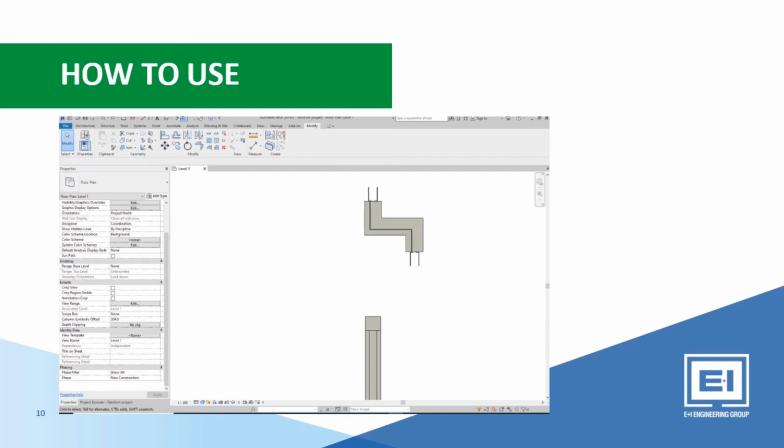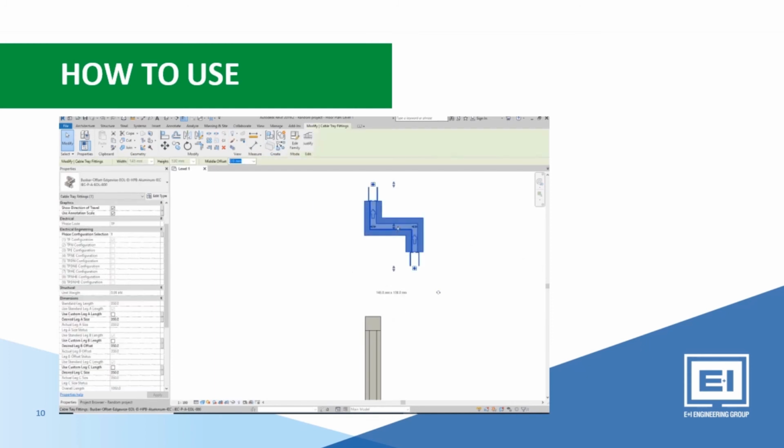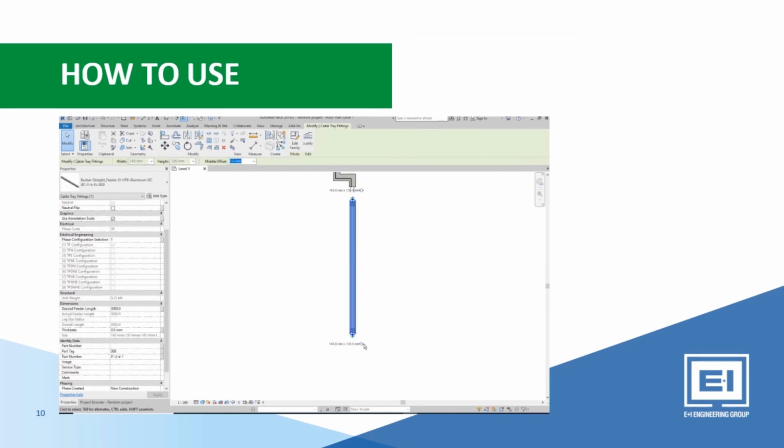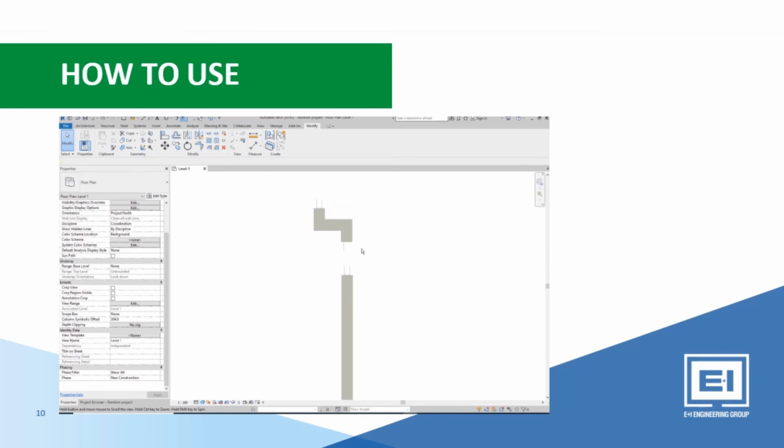Revit also has an Align tool, which can be accessed from the Modify menu. This allows nodes to be aligned together, which helps to speed up model creation, and once the parts have been aligned using this tool, they can be easily repositioned as one continuous section.